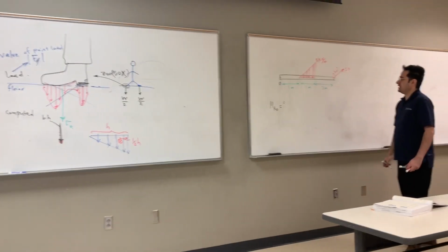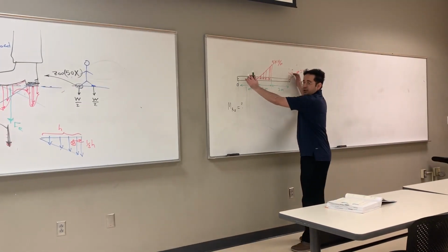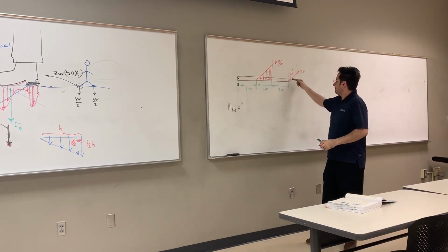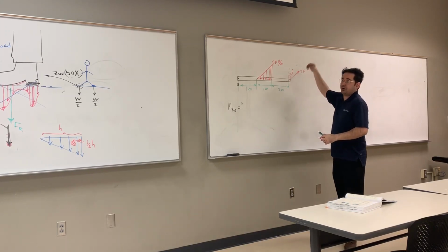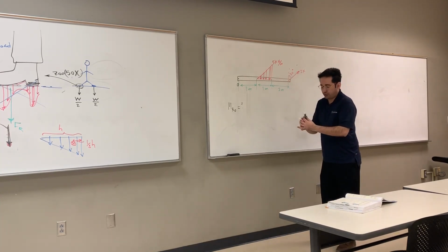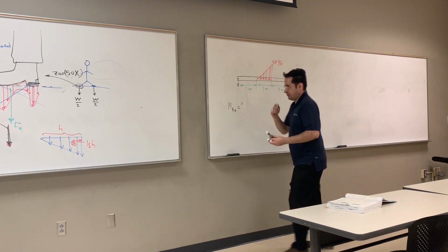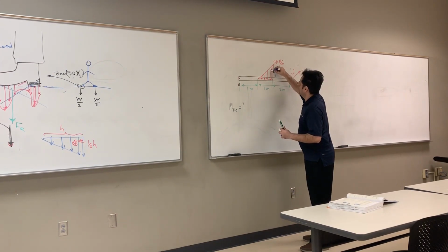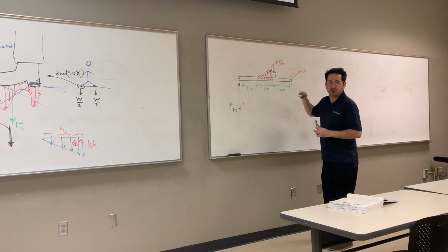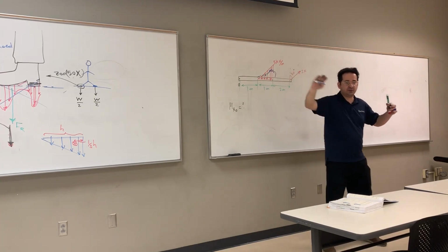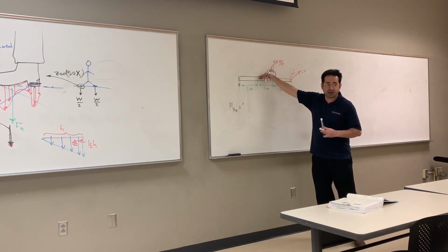So basically, let's say this is a beam. Let's say this is the roof of your building, right? And there is a force here. Let's say one of these I-beams is attached to something. And then there is some snow. Let's use blue color. Here you have more snow, and here you have a smaller amount. Or some loads. Then you can estimate the loading with a distributed triangular load, because here you have more loading than here.